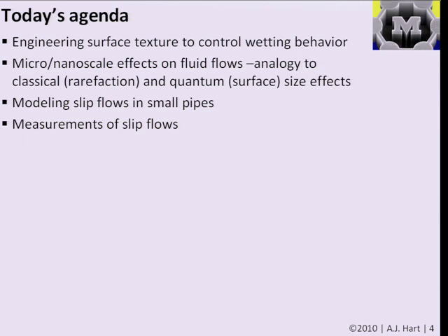Well, that's not actually true, but when we model the flow through a macroscopic thing like a macroscopic pipe, and we'll define the dimensional limits in a while, there is actually a bit of slip. But because the interactions within the fluid, like molecules colliding with molecules within the fluid, are so much more important than the interactions between the molecules and the wall, it doesn't really matter whether we say there's slip or not. And if we say there's no slip at that scale, it's a lot easier to solve the problem.